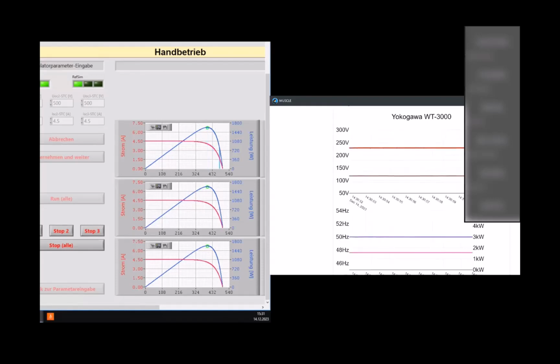Now we can see the view on the right side. And on the left side, we can already see how the inverter reduces its power because of the overfrequency. The frequency we can see on the right side in the lower part of the figure. And now on the left side, the blue lines totally disappeared. That means that no power is injected to the grid anymore. So the inverter disconnected because of the overfrequency. So we go back then to the presentation.